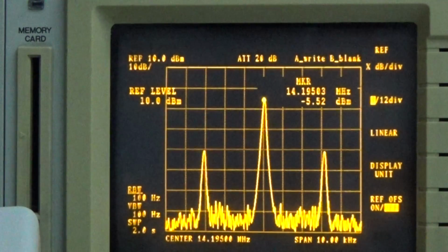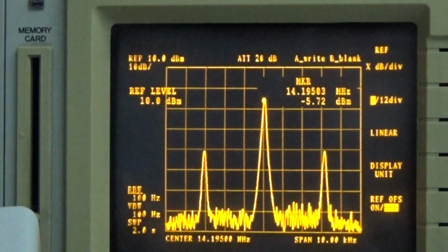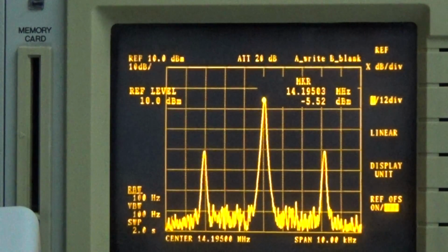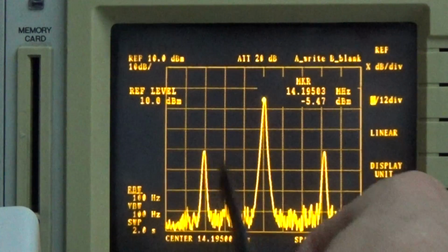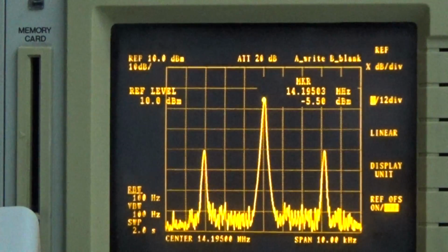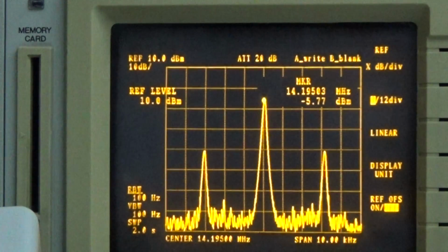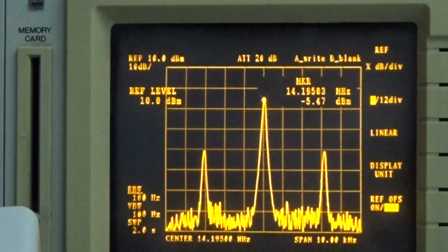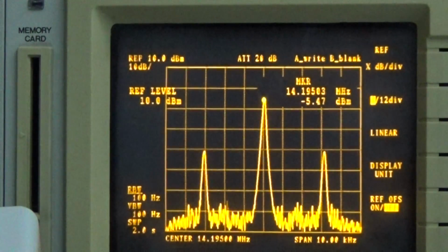So to transmit a signal which is carrying only a 3 kilohertz tone, or 3 kilohertz audio information, you always need 6 kilohertz bandwidth, and that means this bandwidth is needed within the entire bandwidth which is available on the respective band we are working on.